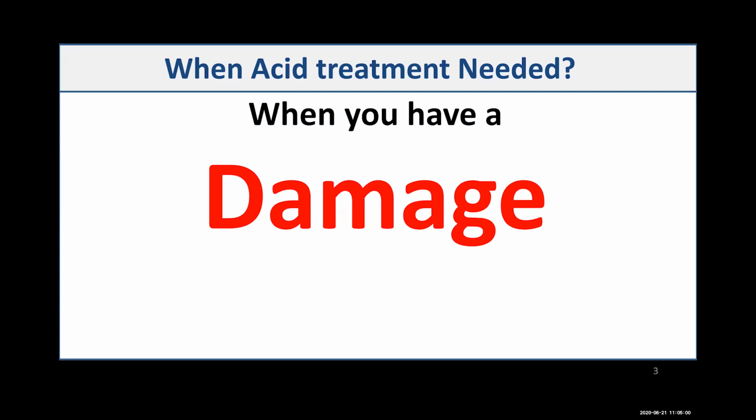That's the only case in which you pump acid. And that is the objective of the acid: either to bypass the damage or remove the damage. And hopefully by removing the damage, you are restoring your formation permeability to the original condition, and hence increasing your damaged well permeability to a higher value.